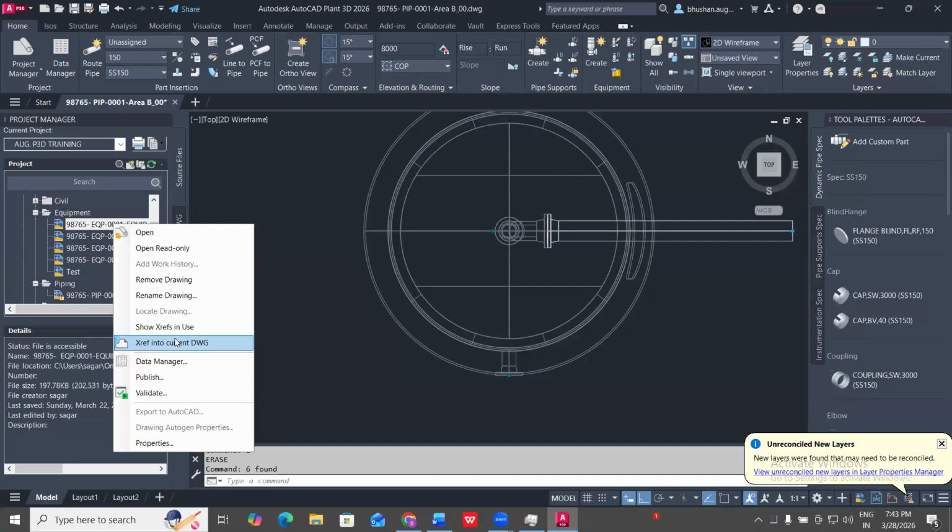And if your model has been created in AutoCAD 3D modeling, or in different software, or it is a STEP file, you can use that, but it will not connect your pipe correctly to your nozzle. You will select the node point, but it will not show you the node point.